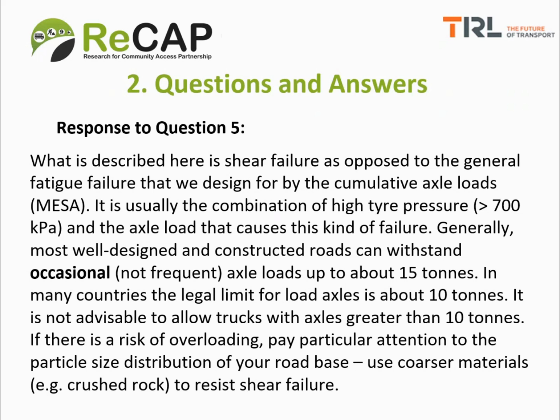Generally, most well-designed and constructed roads can withstand occasional, and I want to stress the word occasional, not frequent, axle loads up to about 15 tons. In many countries, the legal limit for axle loads is about 10 tons. It is not advisable to allow trucks with axles greater than 10 tons on your village roads.